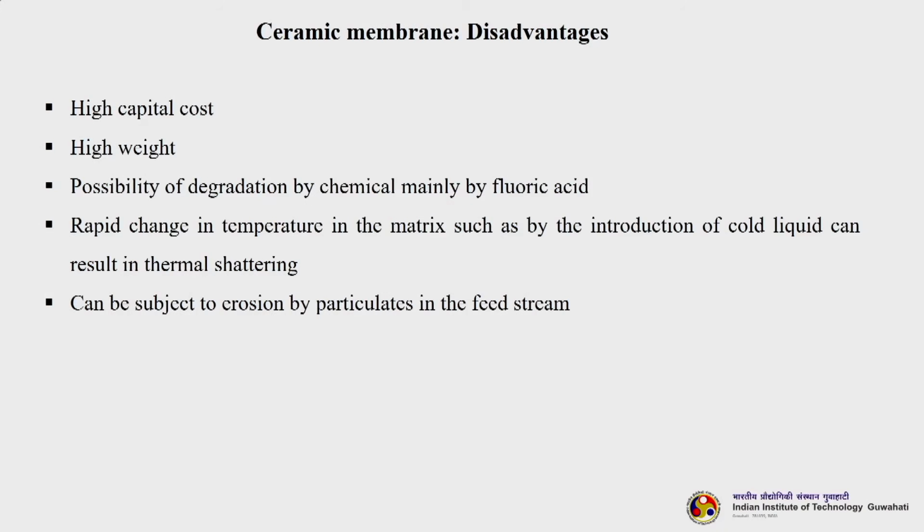Again, the disadvantages, we have been discussing this actually: high capital cost, and weight is a big problem, so carrying and transportation is also a problem. There is also the possibility of degradation by HF, hydrofluoric acid. If you are using it somewhere hydrofluoric acid is present, then they will slowly degrade. Rapid change in temperature in the matrix, such as introduction of cold liquid, can result in thermal shock. So, this is a disadvantage.